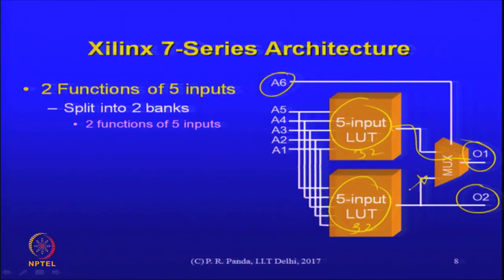So, this is fine when we have a 6-input LUT and we want to implement 2 5-input functions. Right. We can similarly have a criterion for 3-input functions also, 2-input functions also. So the question is, do we have only this, that we have a 5-input LUT fixed and 1 mux outside, or inside that 5-input LUT also there is a mux encoded according to that?